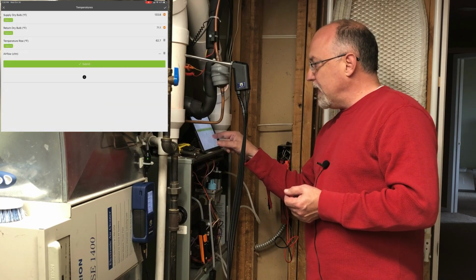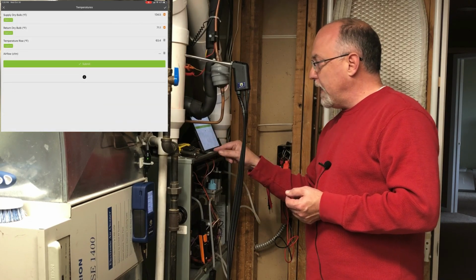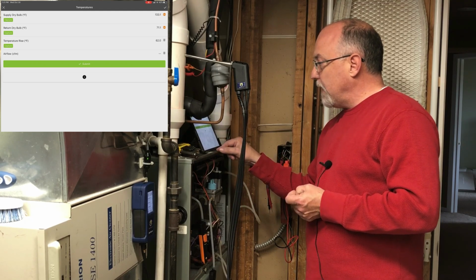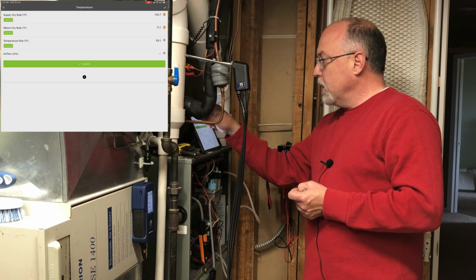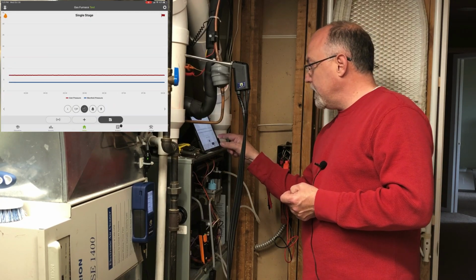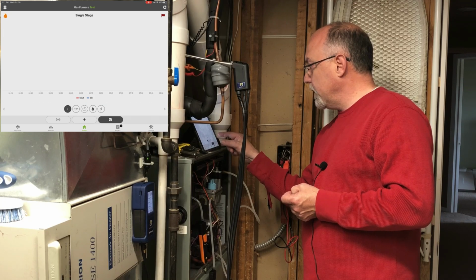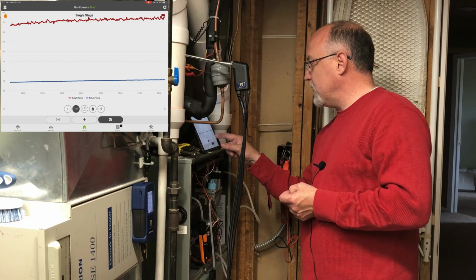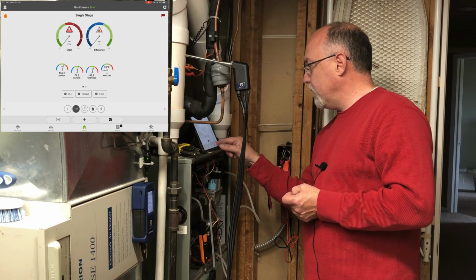I can capture those temps if I want to, or I can just leave them run. Right now, I'm just going to leave them run. I have about a 62 degree rise, 63 degree rise across my heat exchanger. So if I go back here, I go to trending again, I can probably look at the temperature rise. We'll see here if that's on this. Supply and return. No, we don't have temperature rise on the trending by itself. I'll probably have the guys do that for us.